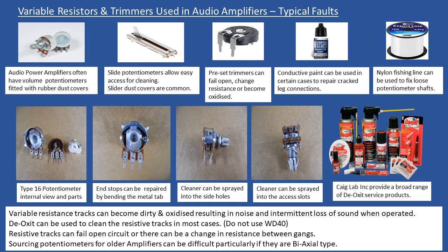What I'm referring to here is that when you have these contacts, they are riveted directly onto the resistive track, and sometimes they can become a little bit loose, right? So nothing of any significance, but it's not taking any high level of stress. So what I can do is repair that. This isn't the resistive part of the track, this is the non-resistive part, because it's conductive paint, it should be lowest possible resistance, and then I can paint this on, so it's quite thick, and that will act as a very good repair in those types of cases.